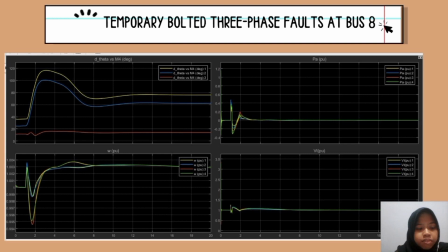After the temporary fault between 1 and 6 seconds, the rotor angle and speed start to increase because the power injected into the prime mover exceeds the power extracted from the rotor, causing the system to become unstable during the initial stage of the fault injection. The circuit breaker will initiate a tripping signal and stabilize the system. Nevertheless, the system begins to stabilize once again at 6 seconds when the temporary fault disappears.